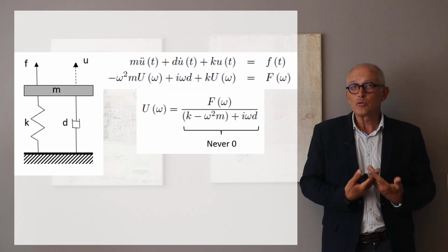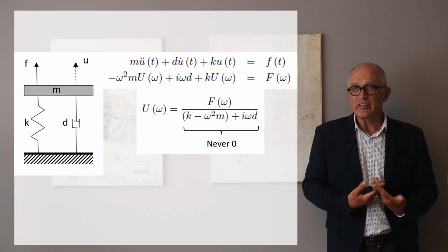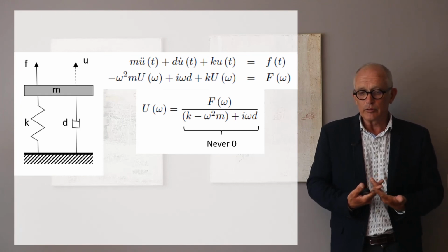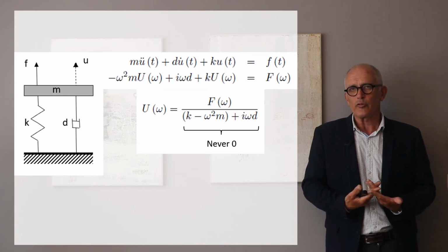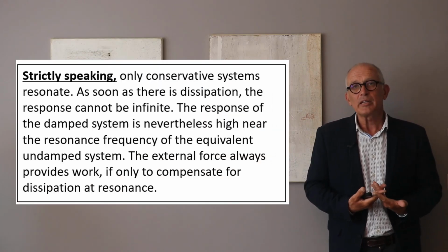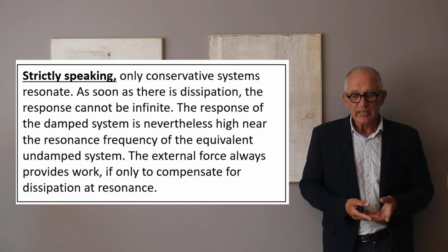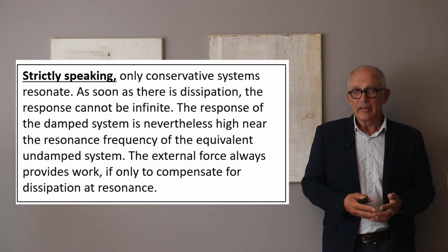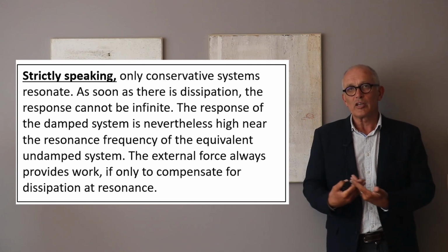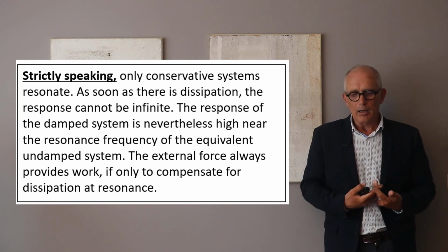And you see that as soon as there is any damping, when d is different from 0, you never divide the force by something that becomes equal to 0. So, strictly speaking, only conservative systems do resonate. There is no frequency at which the system responds in an infinite way.